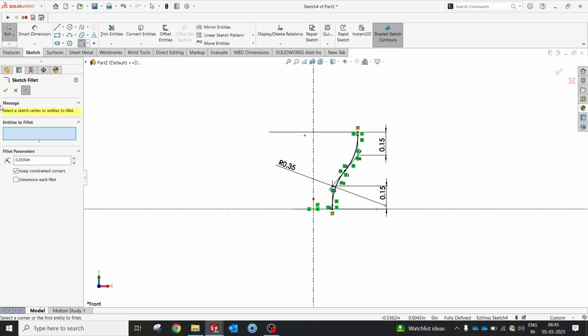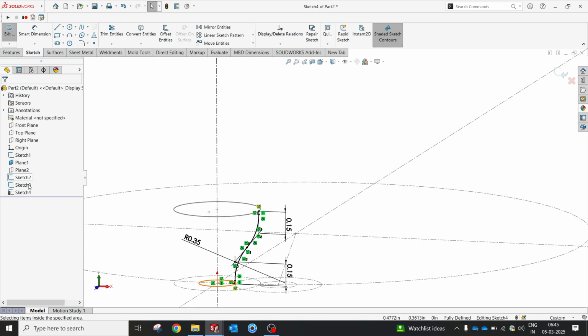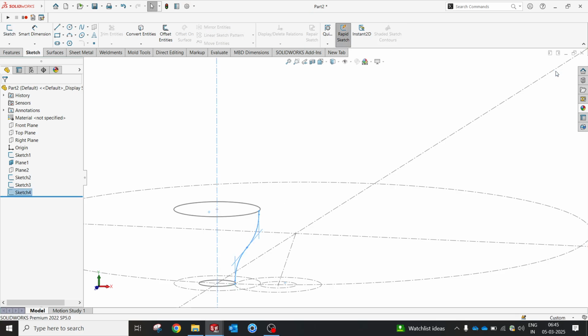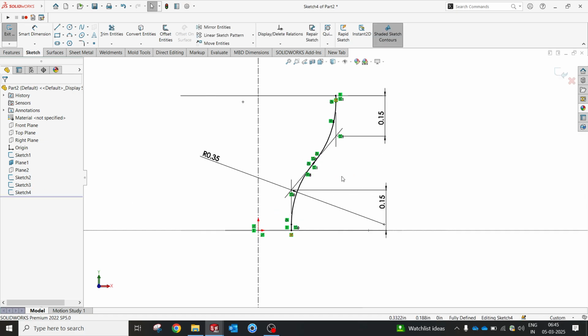As I said, ultimately, if you know the diameter, we can select the diameter from the sketch. As a single profile, you can do the revolve without having sketch 2 and sketch 3. But in order to explore the option in loft, we are trying to increase the number of sketches.